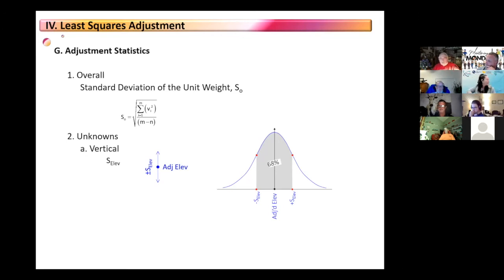For the individual points, now that we've adjusted, say it's elevations or horizontal coordinates, now we want to have something that we know about the quality of those adjusted quantities. And we added up a bunch of numbers together before for our measurement, and we computed the standard deviation of it and the error, the most probable value. Those were our indicators for a measurement of a particular thing. In a least squares adjustment, when we do an elevation adjustment, or vertical adjustment, we wind up with an adjusted elevation and we wind up with a standard deviation of it. That basically is the same thing as what we had when we dealt with a measurement of an object: the standard deviation gave you 68% of the area underneath the curve, or it gave you the 68% confidence interval. If we wanted to have the 95% confidence interval, then we multiplied it by 1.96, like we did before. So it's basically the same thing as we had before, because it's only acting in one direction, vertical.